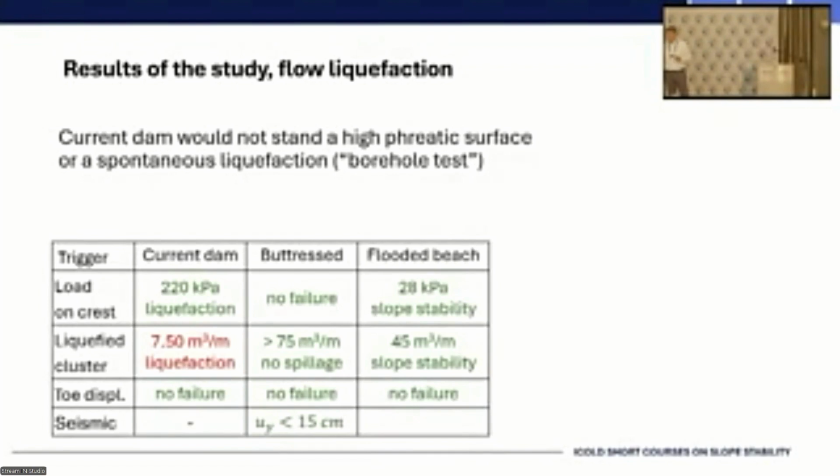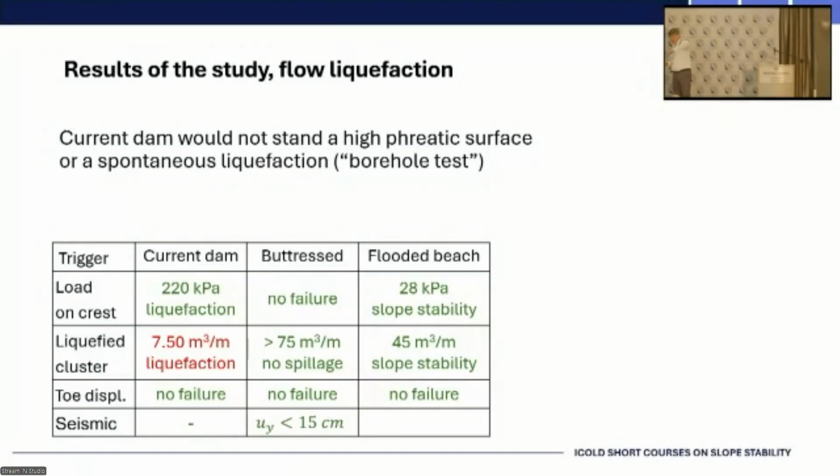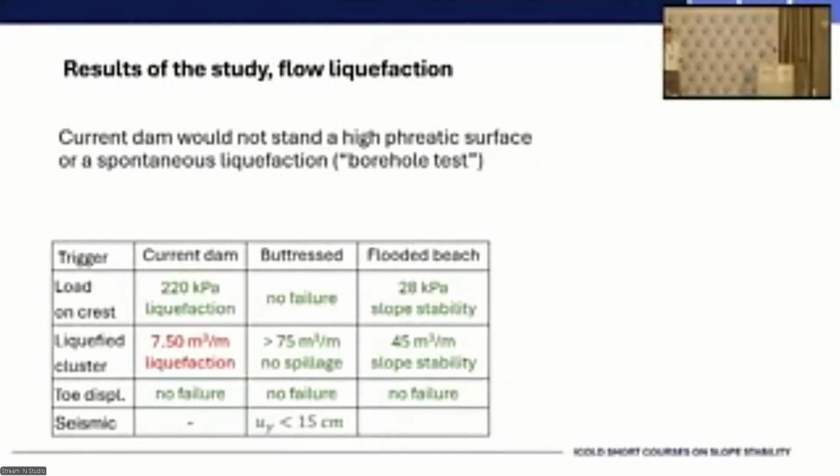We don't know. Look, we're talking about 7.5 square meters in the mesh, or cubic meters per meter, but along the entire thing. The truth is that because liquefaction is inducing propagation of pore pressure, you don't need much of an initial volume to start a propagation. So it's an indication of where you are sitting, and this is related to the factor of safety of 0.39. These 2 things come from the same sources. And remember, all this is controlled by the 0.04 USR.